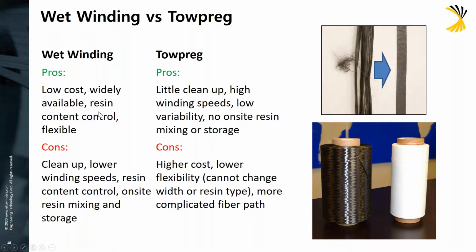Cons are the cleanup. It is a messy process. You have lower winding speeds. Your resin content and control is also a negative because you have to control that on site. And the mixing and storage of the resin and the chemicals associated with it can be a burden.